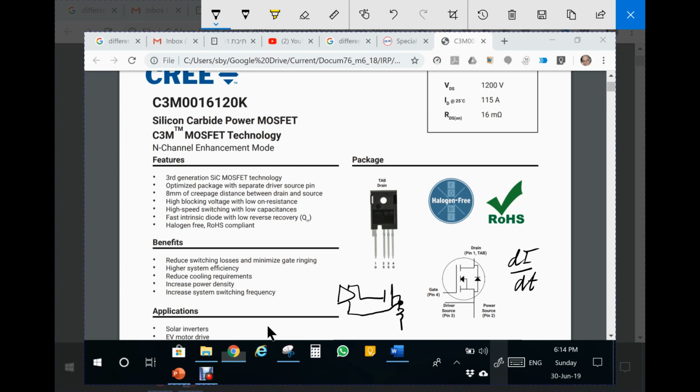One is connected directly to here, and one is connected to the gate. These are the outputs, and here is the input. And then there is a ground, and of course there is a ground to the driver. So this is a special driver which has uncommitted output transistors. Say it's a sort of a transistor like this coming out of the driver, not connected to the ground, so that you can connect this uncommitted point to this Kelvin. By this, you overcome the issue of this.